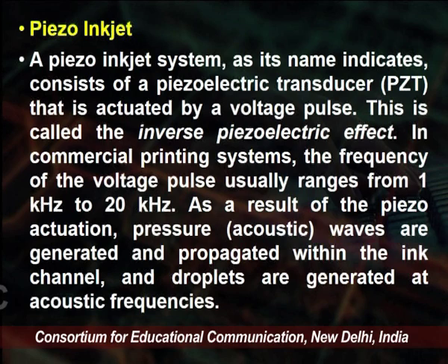As a result of the piezo actuation, pressure waves are generated and propagated within the ink channel, and the droplets are generated at acoustic frequencies. Commonly, bipolar waveforms are used, along with a brief description of the significance of each segment of the waveform.